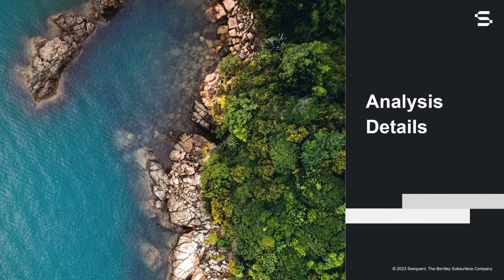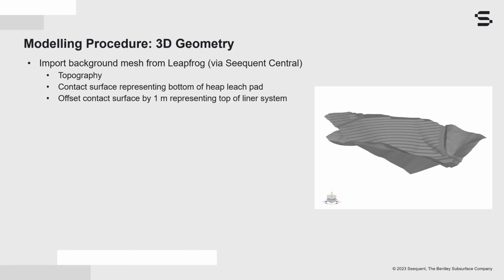Let us now review the steps for setting up our coupled seepage and stability analysis in GeoStudio. The first step in setting up a numerical analysis is to create the geometry. In this case, we will be using components from a geological model created in Leapfrog to generate the 3D domain. We will start by importing surfaces as background mesh that represent the topography and the contact between the heap leach pad and the underlying bedrock.